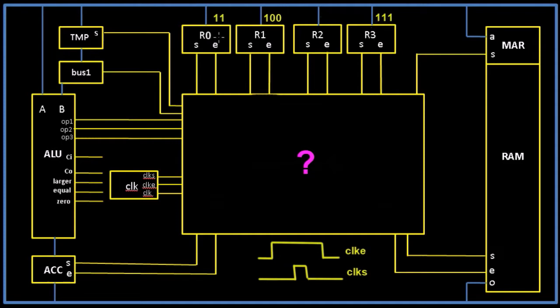The method that we'll work through, and we're going to work through this another twice through this video, so you'll really get to understand it. So the method that we're going to use is, first of all, we're going to put R1 onto the bus. So we have to have the enable go high. It will put this value here, which is 4, onto the bus. And then the temp is going to set, so it will set that number in this temp register. The temp goes low, and that's it held within this point here.